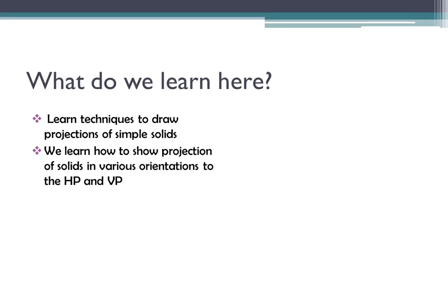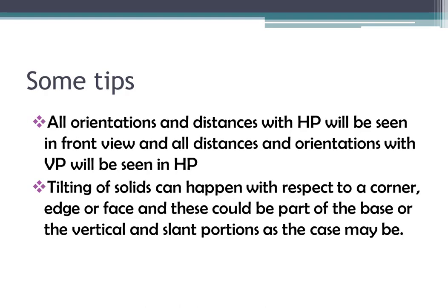So what we learned here, we learned techniques to draw projections of simple solids. Then we also learned how to show projection of solids in various orientations with respect to the horizontal and vertical plane. And some tips to think about. All orientations and distances with HP will be seen in front view, and all distances and orientations with VP will be seen in the top view.